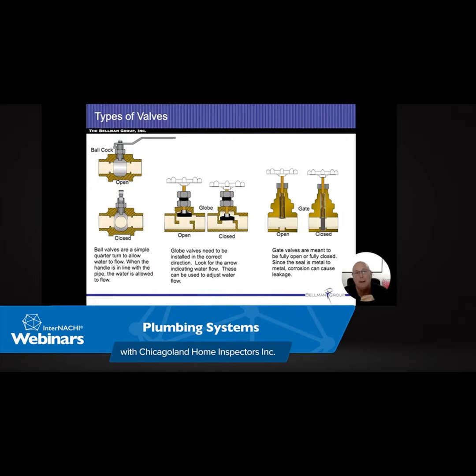But most of the time it's going to end up being a bell and gusset type situation. So we're going to have that bell that's going to hold the other pipe on top of it. It's going to sit inside of it. And then they're going to stuff the lower level of that gap with a waxy rope. And that waxy rope is called oakum. And then they're going to take lead and they're going to heat up that lead and get it into a liquid form.